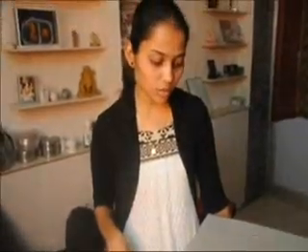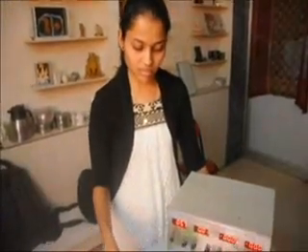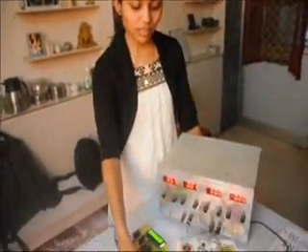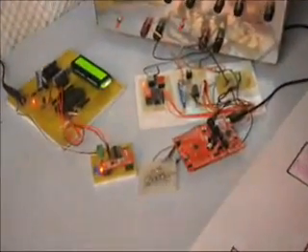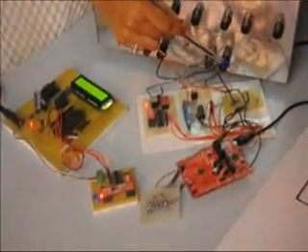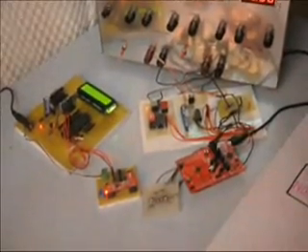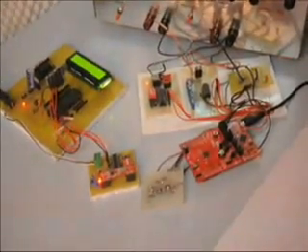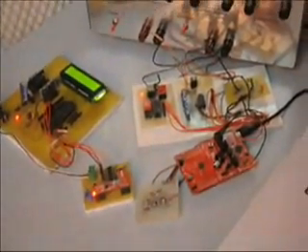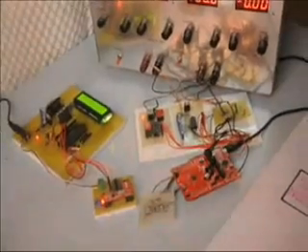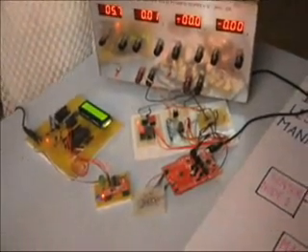This is the circuit of sensor node 1. This is the transmitter section, the receiver section, the MSP LaunchPad kit, and this is the temperature sensor. To perform this load management, we have used a current sensor for measuring the current at different nodes. Based on the load condition, the variation in the current is sensed and sent to the master node. This node to master transmission takes place with the help of an RF module. We have used a 433 kHz RF module. This module transmits the signal for the particular node's current at the present condition.